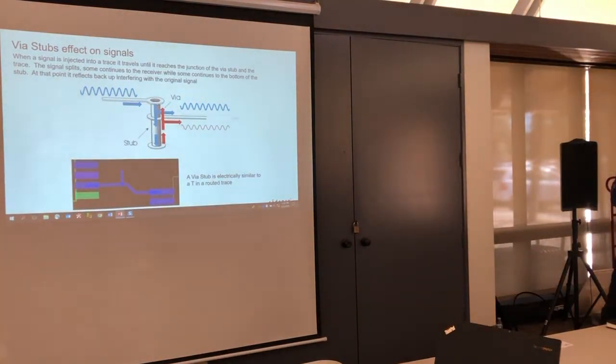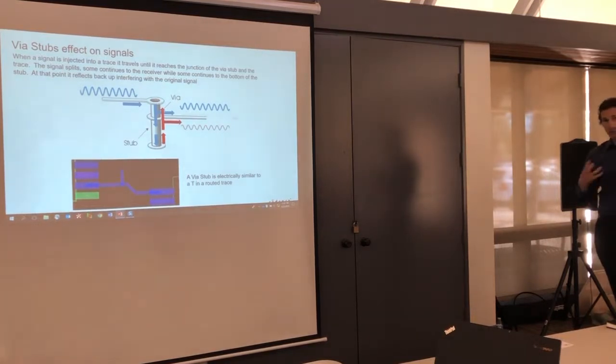Instead of back drilling, you know, a micro via would do the same thing. Which is more cost effective and which is actually better? There's so many trade-offs in that question. From a performance perspective, a micro via is going to accomplish the same thing as back drilling out a through-hole via. What's more cost effective on your design?